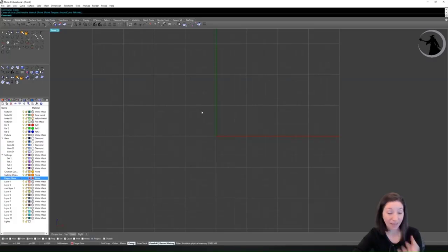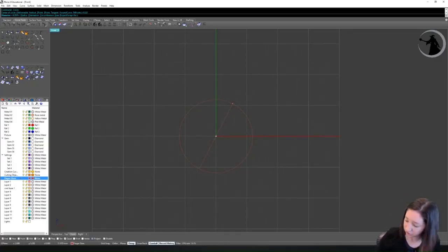So when I accidentally drew the small circle, I can now right click. And if I look at my command line, it'll say center of circle because now I'm in a tool again. So I can try that again, F4, and then we are making a size 5. So this is going to be a 15.76, and you can type that directly into the computer.